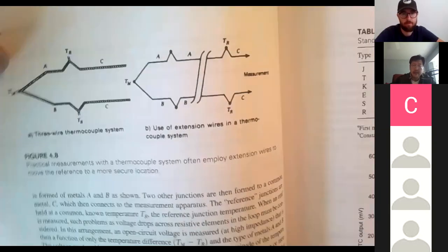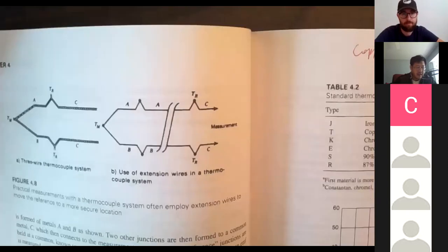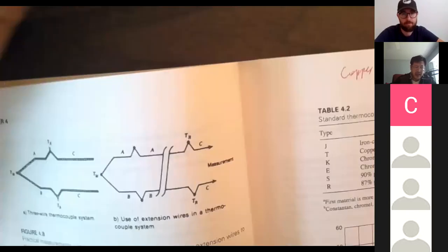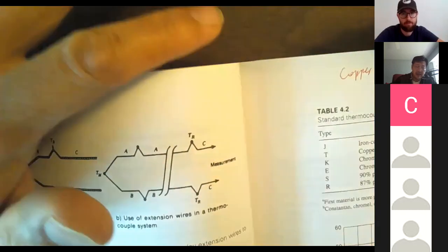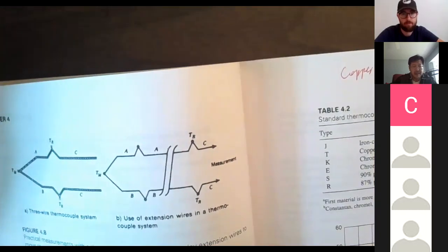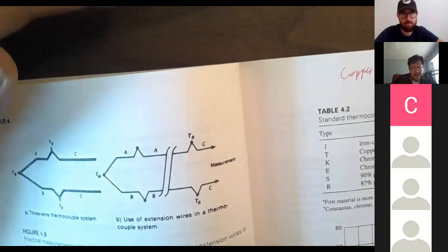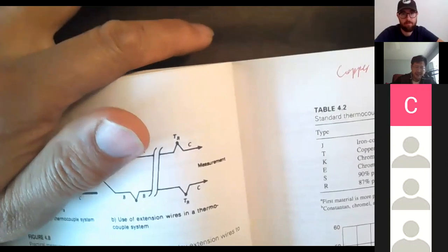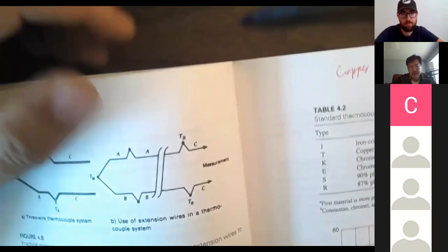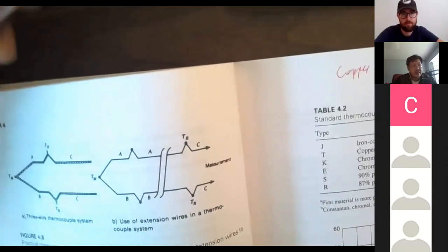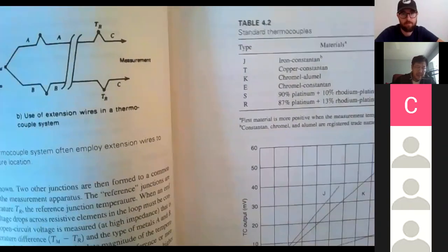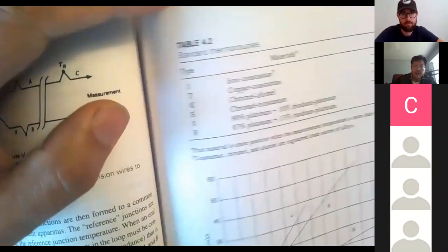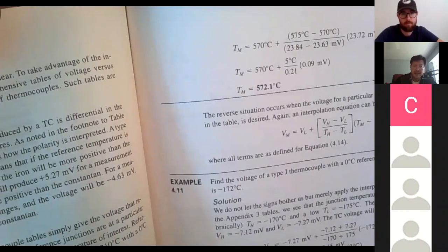It turned out in the furnace, this 120 milli thermopile is attached very close to the pilot flame. So you have a little pilot flame, and on top of the pilot flame is your thermopile. That thermopile will generate 120 millivolts. That voltage will open the valve of your gas pipe.